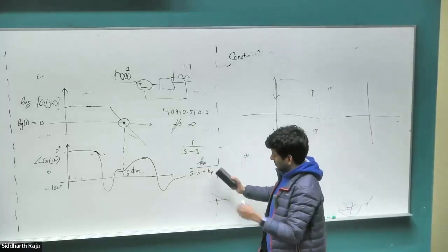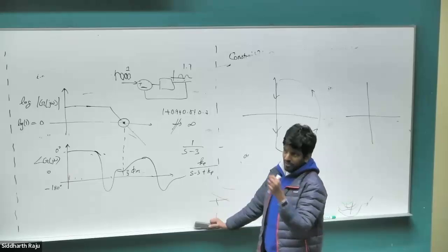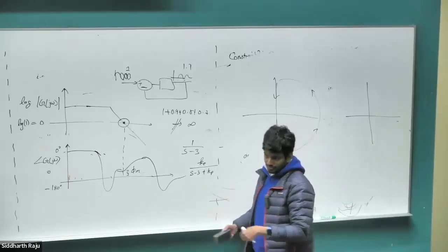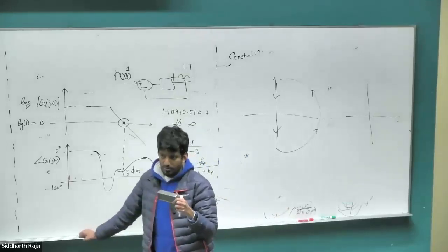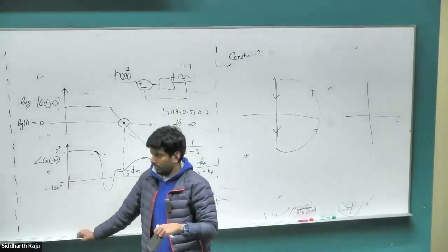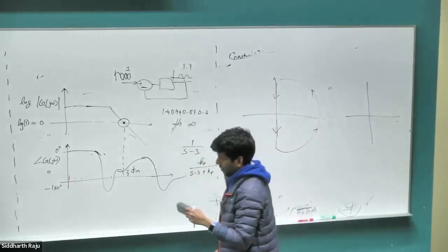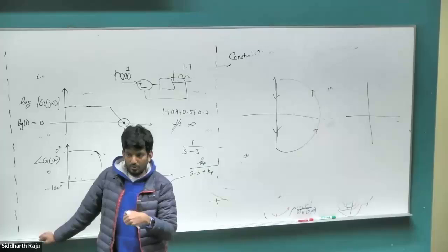Yeah, that's what I was wondering, because a higher Kp would make it stable, but the image appears as if it's going to make it unstable. So this whole analysis only applies for open loop stable systems? Yep, that was criterion 1. So criterion 1 was an open loop stable system, and criterion 2 was the order of the numerator less than the order of the denominator. Okay. Very good question. Any other questions?